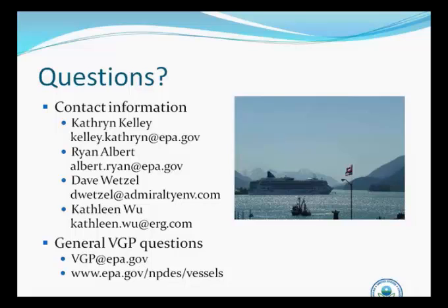Well, I think it's advisable, but it's really going to depend on what kind of testing you're looking for and the holding time for that test, and whether or not you're able to keep the sample under preservative conditions, let's say keeping it cold enough between the time that you collect it and when you get it to the laboratory. I mean, we work with several labs that are an hour away from the port, but they have an adequate plan for getting to the port on time and getting the sample back to the lab. So it's really driven by the holding time of the test that you have and what kind of coordination you can do with the lab.